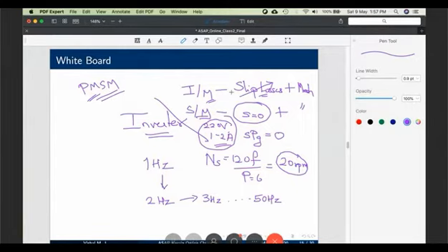Okay, sir. One question. Do you feel this is why a BLDC motor is more efficient? Yeah, PMSM and BLDC are exactly the same. They are the same. The only difference comes in the nature of the flux waveform in the air gap. A PMSM has a sinusoidal flux distribution. BLDC has a trapezoidal flux distribution. That's the only difference. Otherwise, they are essentially the same. Anything more? Okay, sir, clear, sir, continue. No other questions.